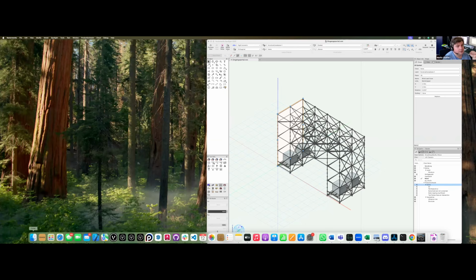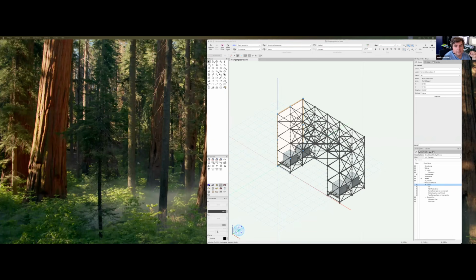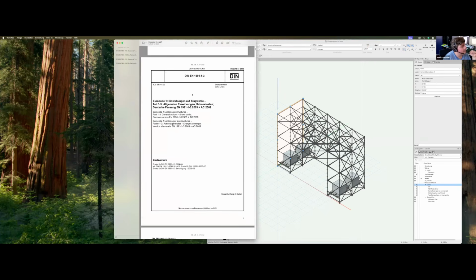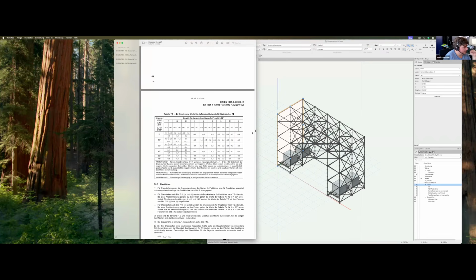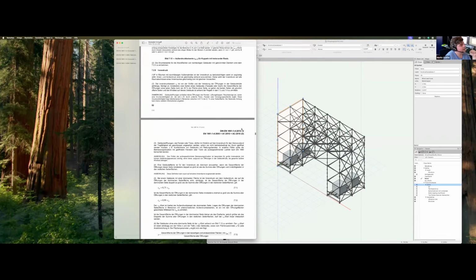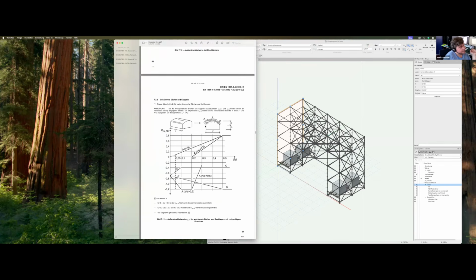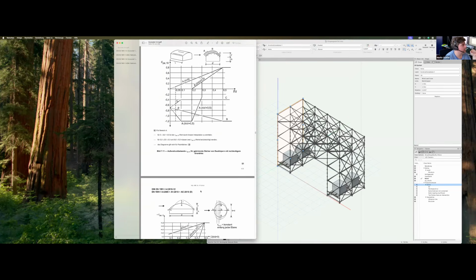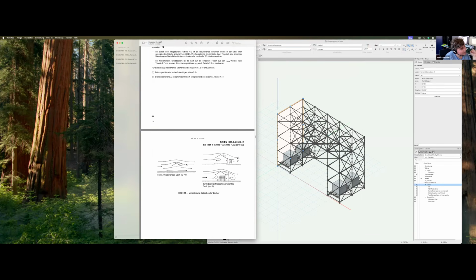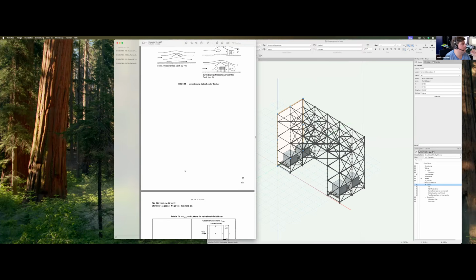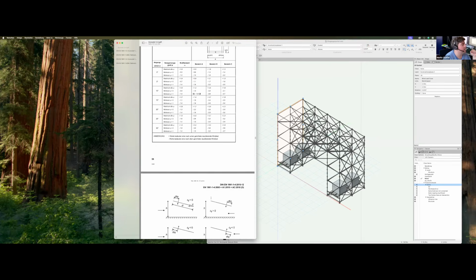Unfortunately, currently as a digital thing, I only have the German norms in here, but in here we have the European one, the Eurocode. Then I just show you the relevant thing. So for example, depending on the roof shape, they define how the forces are applied, or where the factor 1.8 comes from. There's a lot of description in here. For example, how normal roofs are considered, and then it gives you the CF values from here.